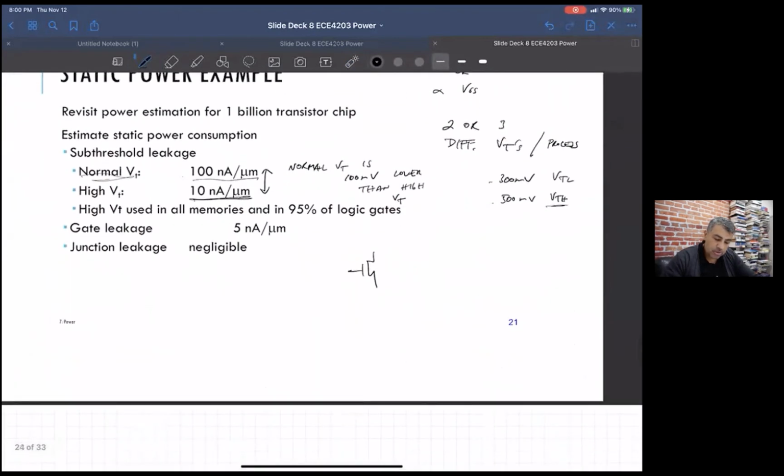So there's the subthreshold leakage. I think we talked about this maybe 4 weeks ago. I don't remember. We were talking about subthreshold currents, but just as a reminder, we have the subthreshold leakage. And this is the one that's a function of threshold voltage, and how far your zero is always a zero. It is how far your zero is below your threshold voltage. That's the important thing. So anyway, that's the subthreshold current.